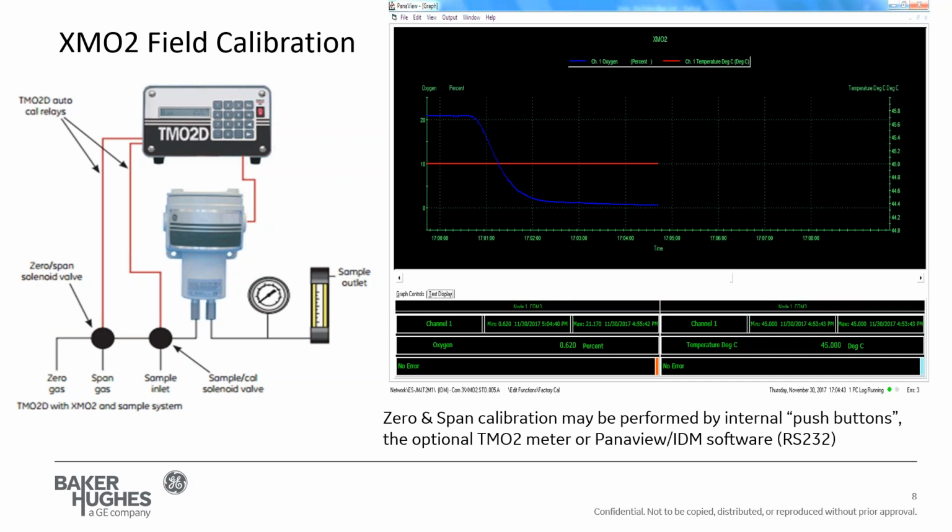Can these sensors be used to measure dissolved oxygen in water or other liquids? No, they're only for gas. And sometimes people also get a little confused with the word vapor. When we say vapor, we really mean something in the gas phase. But sometimes we think of vapor as being, for example, a cloud. When you look at a cloud, that's actually liquid water suspended in the air. It's fine droplets of liquid water suspended in the air. Most vapors and gases are invisible. So we're only measuring with these technologies in the gas phase.